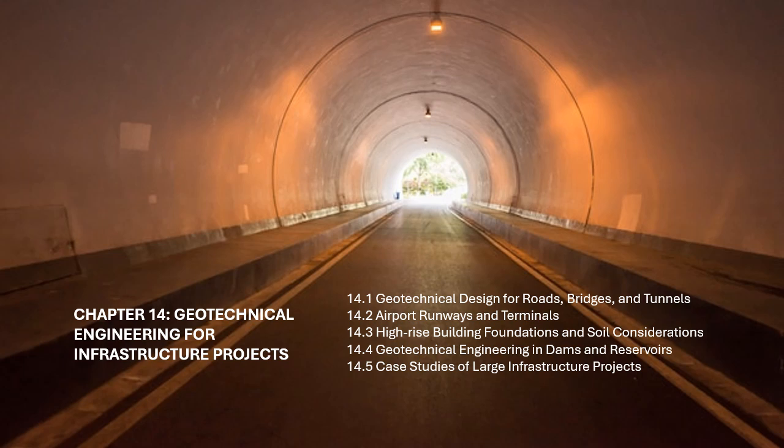Geotechnical innovations. The design incorporated high-strength reinforced concrete and post-tensioning techniques to manage the forces acting on the building. A significant challenge was the large volume of concrete required for the foundation, which needed to be poured in a continuous operation to avoid thermal cracking. Specialized cooling systems were also used to manage the temperature of the concrete as it cured.